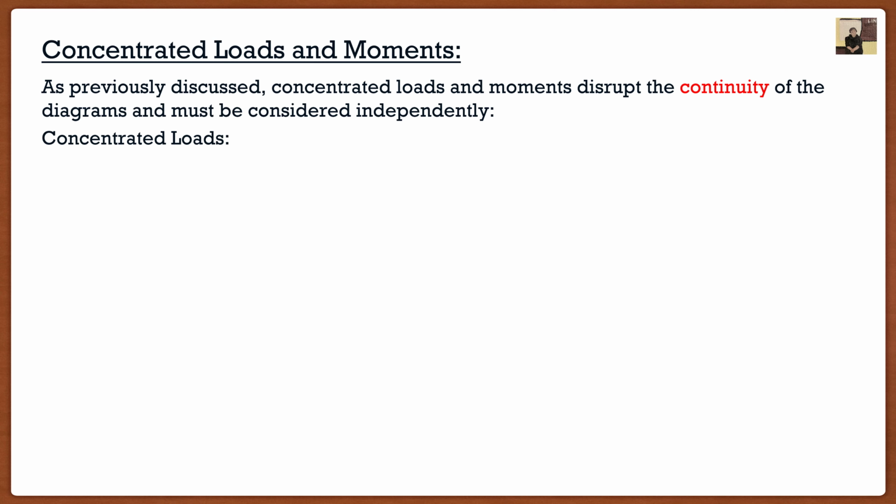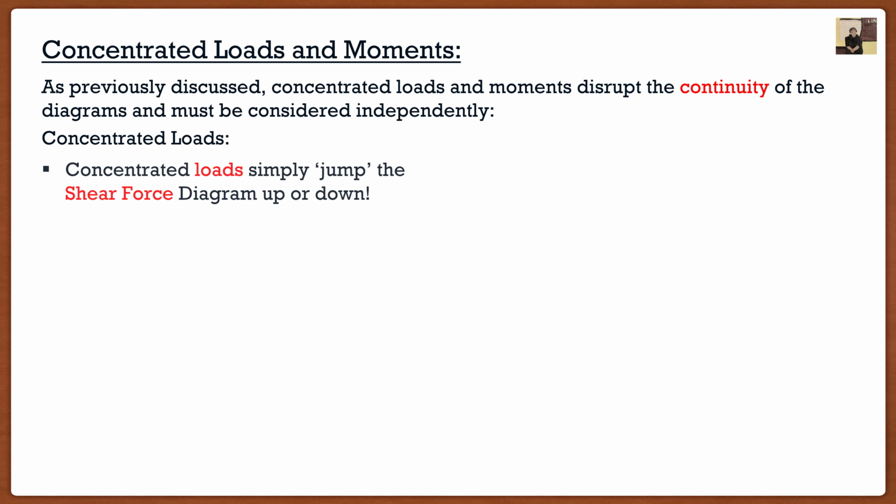Now it's actually very simple, very intuitive, and you guys may have already picked up on it in the last video. Concentrated loads simply jump our shear force diagram up and down. So here's the first key. Concentrated loads impact our shear force diagram, and all they do is jump it up or down.